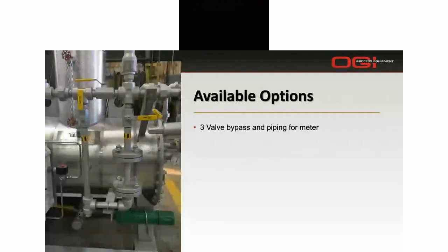And then if you do buy your own meters but want to install them on your own, then you could also get this option. It's what we call a 3-valve bypass. Essentially, we provide the piping, the block valves and the spool piece. Just tell us what those dimensions need to be, and we can size it properly. When this arrives in the field, your technicians would remove this spool piece and install the meter that you prefer.